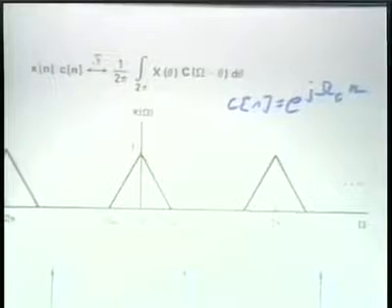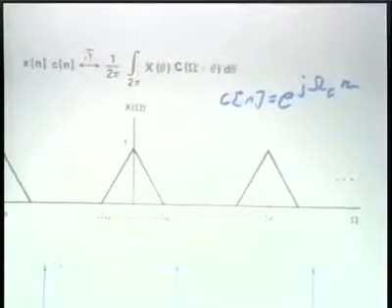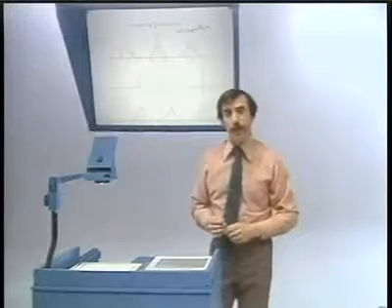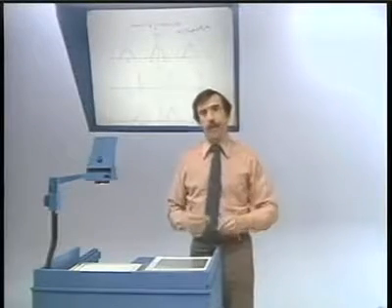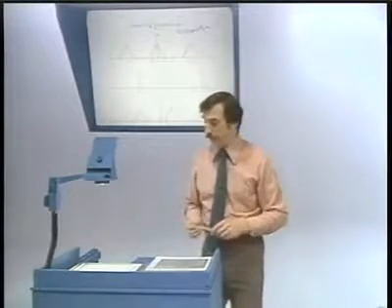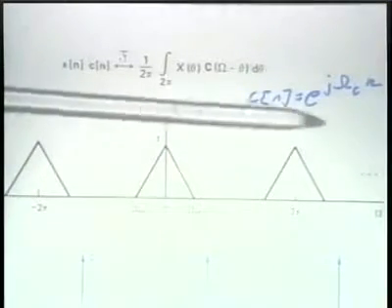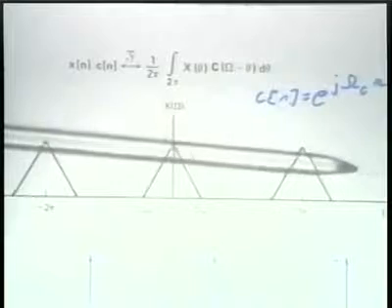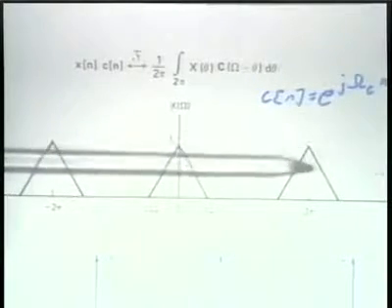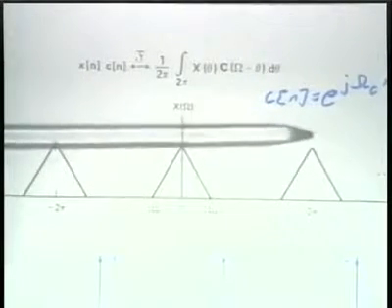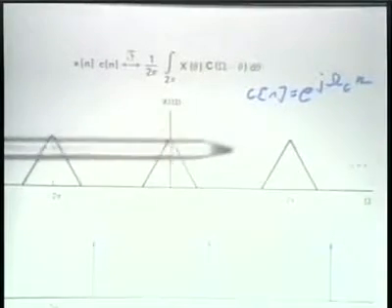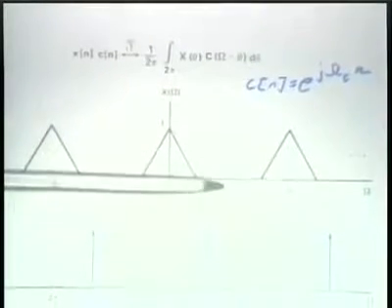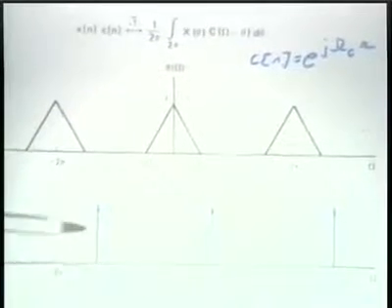And let me stress, by the way, as I did in the continuous time case, that I'll tend to suppress the phase angle, which, of course, can be associated with the carrier also. All right, so we have then the spectrum of the modulating signal. The spectrum of the carrier signal, if this is the carrier, is an impulse train, and that impulse train I've indicated here.